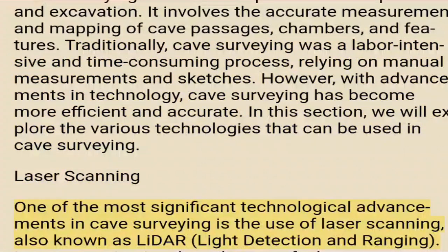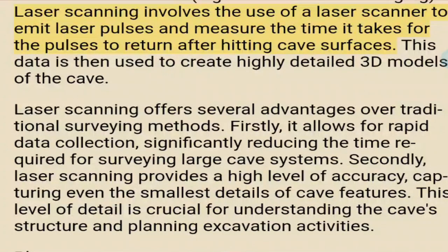Laser scanning. One of the most significant technological advancements in cave surveying is the use of laser scanning, also known as LiDAR, light detection and ranging. Laser scanning involves the use of a laser scanner to emit laser pulses and measure the time it takes for the pulses to return after hitting cave surfaces. This data is then used to create highly detailed 3D models of the cave.